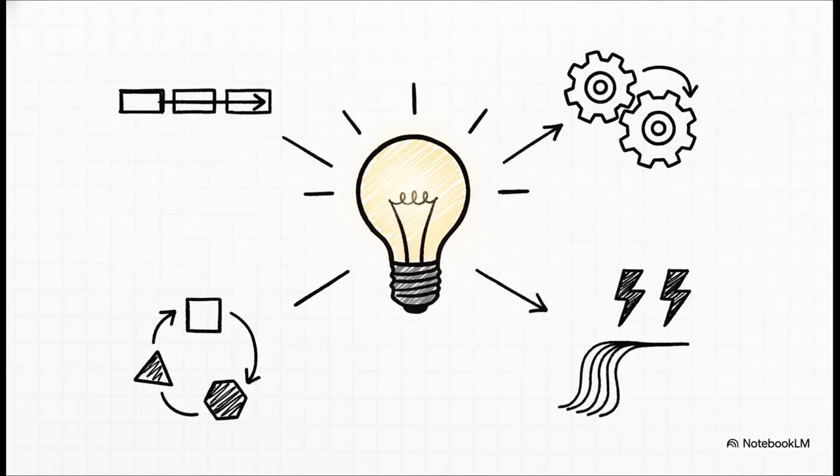Let's do a super quick recap of your major takeaways from this explainer before your exams. Registers, they use N flip-flops for rapid-fire data storage and movement. Counters, those are your sequential state machines for tallying up events and keeping time. Remember to nail down those mod formulas. Binary is 2 to the power of n, Johnson is 2 times n, and ring is simply n. And finally, don't forget the core architecture difference. Synchronous counters use one simultaneous clock for speed, while asynchronous counters rely on that cascading ripple effect.